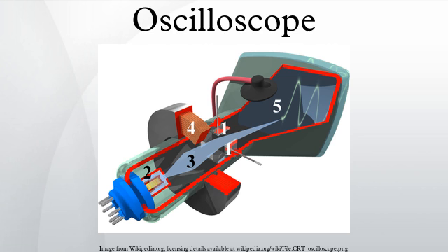Analog storage oscilloscope. Trace storage is an extra feature available on some analog scopes. They use direct view storage CRTs. Storage allows the trace pattern that normally decays in a fraction of a second to remain on the screen for several minutes or longer. An electrical circuit can then be deliberately activated to store and erase the trace on the screen.